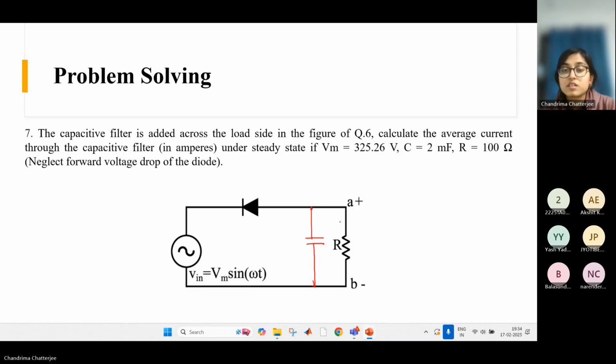Okay, just let me explain. Just tell me one thing. If there is a signal which is pure AC, it can be of any shape, not just sine or cosine. But suppose this is pure AC. What do I mean by pure AC? A pure AC signal means the area under the positive half is equal to the area under the negative half, right? That is called a pure AC signal. So for a pure AC signal, any random shape it may have, what is the average value?